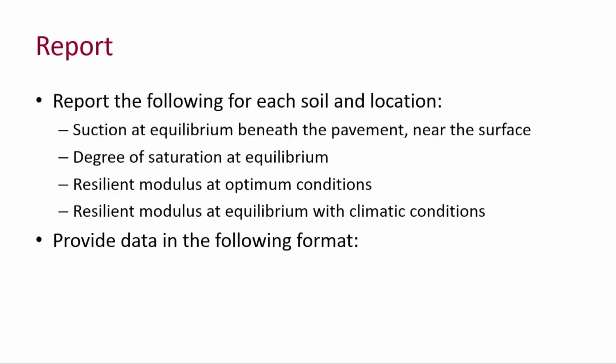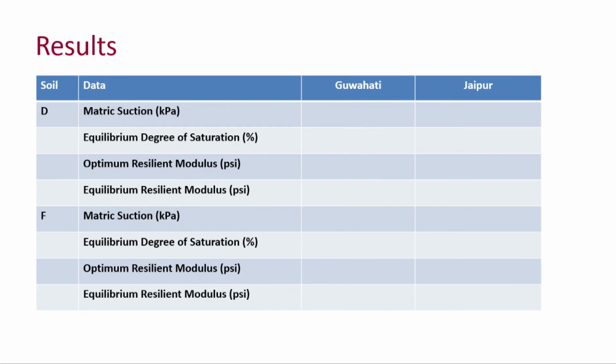So you report the suction at equilibrium. You report the degree of saturation, the resilient modulus at optimum, and the resilient modulus at equilibrium. It's pretty simple. There are 4 equations that you need to follow.